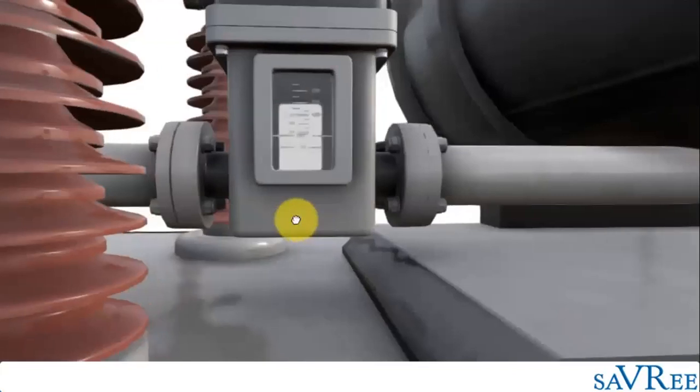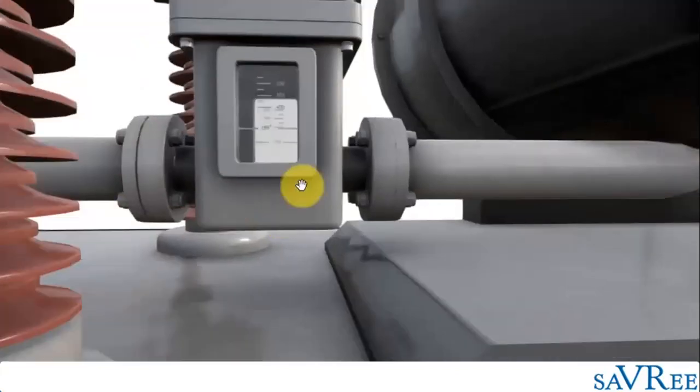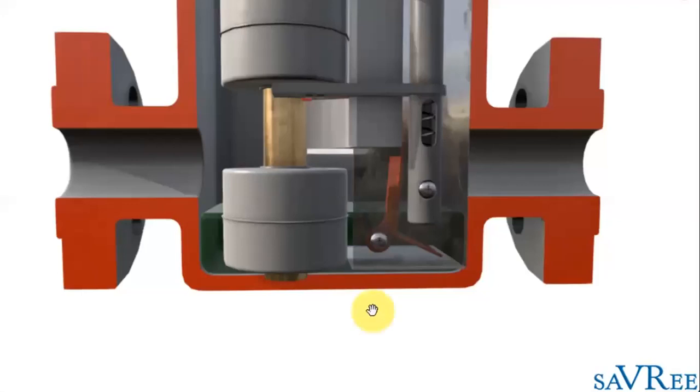If, however, we set off that float alarm within the Buchholz relay, then we've got a problem, because we know we're losing liquid. And that is a big issue that could lead to what's termed a catastrophic failure, and that's what we don't want. So what we'll do, we'll have this second lower float here, and that will set off an alarm. In fact, it will actually set off an alarm and shut down. So this is another shutdown trip.